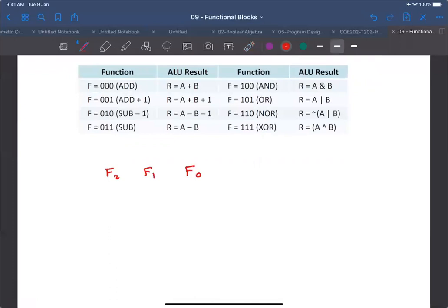Doctor, sorry, but we are going to need to use 2 multiplexers, right? One for the most significant bit, and then one for the other operation. So if it is Boolean or arithmetic, and then choosing from Boolean or choosing from arithmetic. Yeah, we have 8 functions basically.